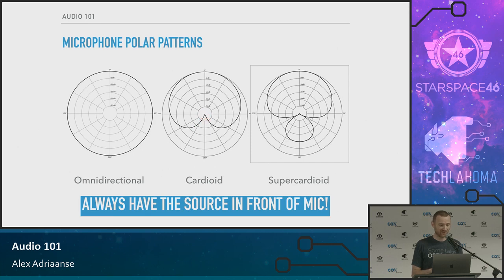So in other words, this mic right here, because it's a cardioid mic, at least if I remember correctly, will reject all sound coming from the back. I'll demonstrate that real quick. I'm just going to be talking and turning the mic, and you hear very little. Talking from behind it, almost nothing is being picked up. I'm not perfectly behind it. And as I go to the other side, it comes back on.